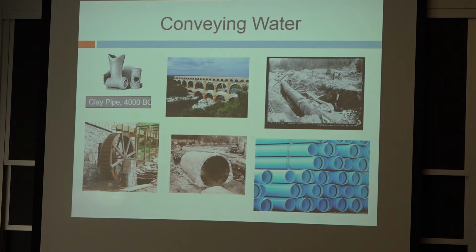And today you're seeing these large cast iron pipes or ductile iron pipes in a lot of these major cities. They're 100+ years old. One of the things that happens with cast iron over time is it can become embrittled, and you can get stress cracking and issues just by it being so old. So as infrastructure ages, now they want to go in and put in the latest and greatest materials. They're switching to more polymeric type materials as well.